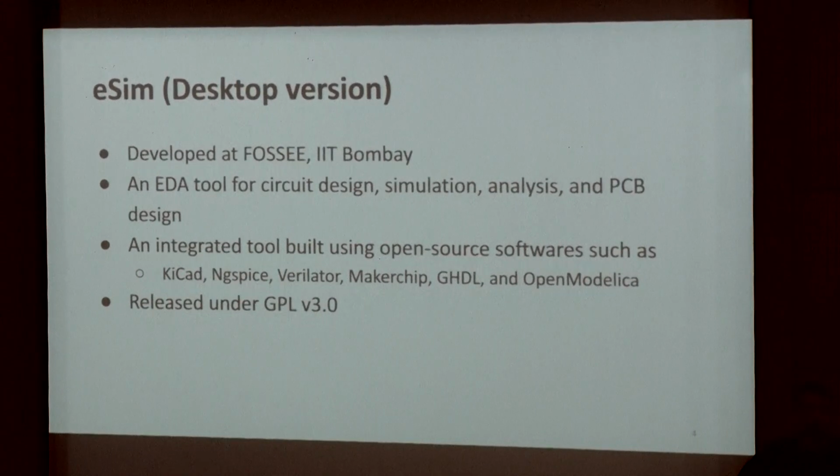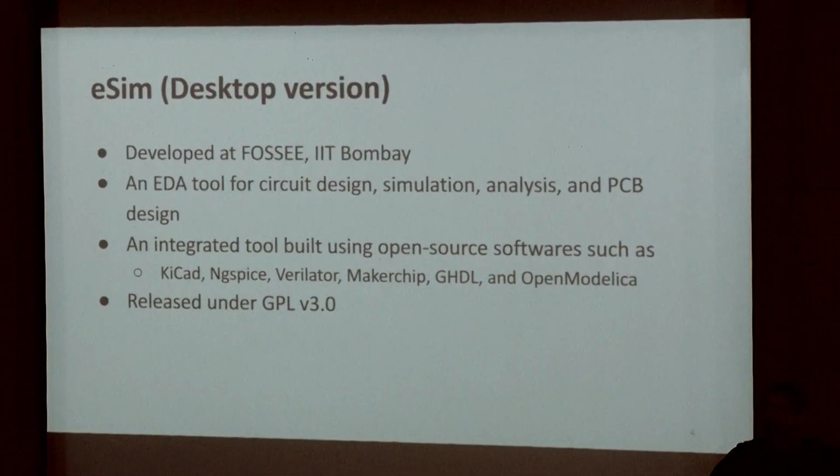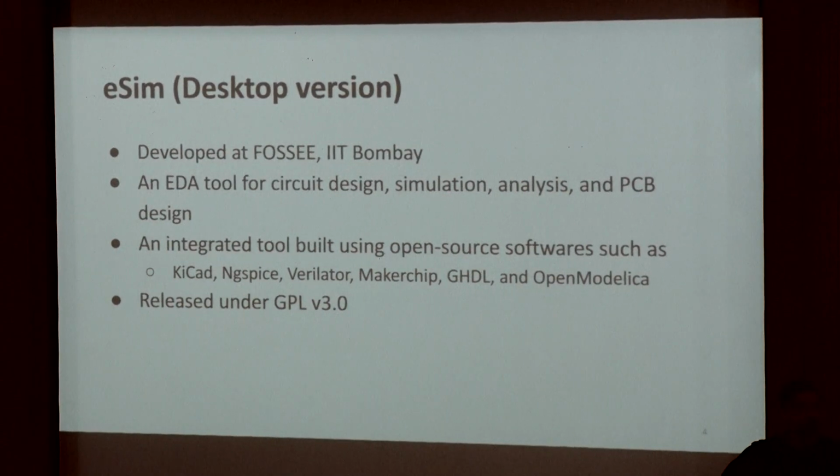Verilator: how many of you have heard of HDL programming, hardware description language? Yes, so you may be aware of Verilog. So Verilator is a Verilog simulator. Similarly, there is also an open source tool called Makerchip. It is a web IDE, so one can run Verilog or Transaction-Level Verilog, a higher version of Verilog, in the web IDE and check the synthesis waveforms and all.